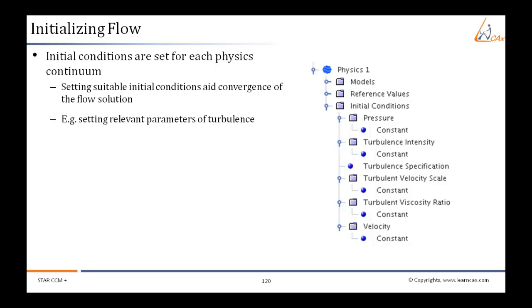Initial conditions are set for each physics continuum. Setting suitable initial conditions aids convergence of the flow solution.